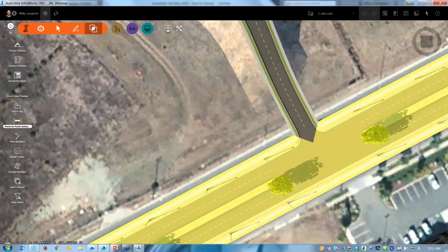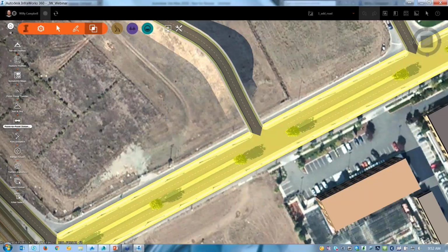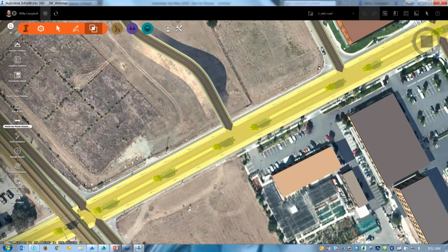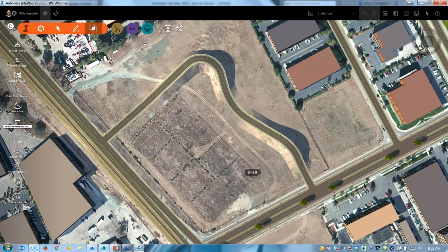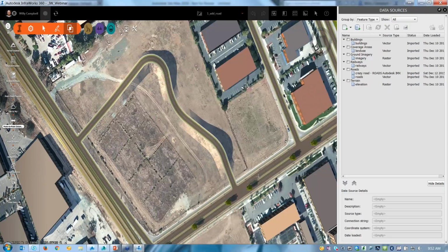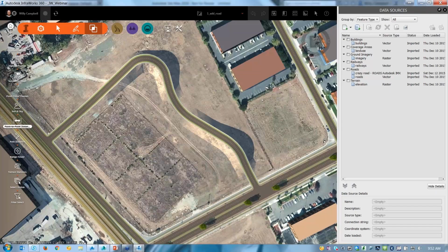So we'll go back to the model. And what that warning is saying is that the road is a spline object, and DAE only understands geometry, and the spline is not geometry. And it was saying that that geometry will actually not be exported as part of the export, right? Well, it can't export it because it's not geometry, but yes. Okay, so it won't be included. So we'll get basically the rectangle and then the vehicles on their path.